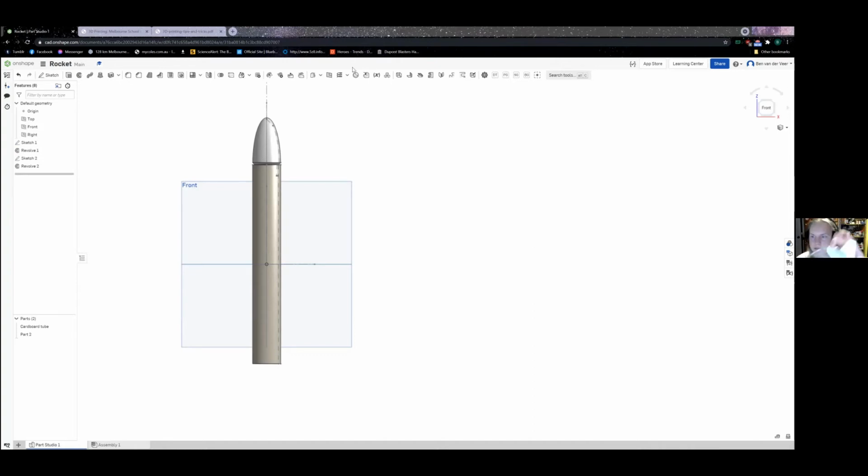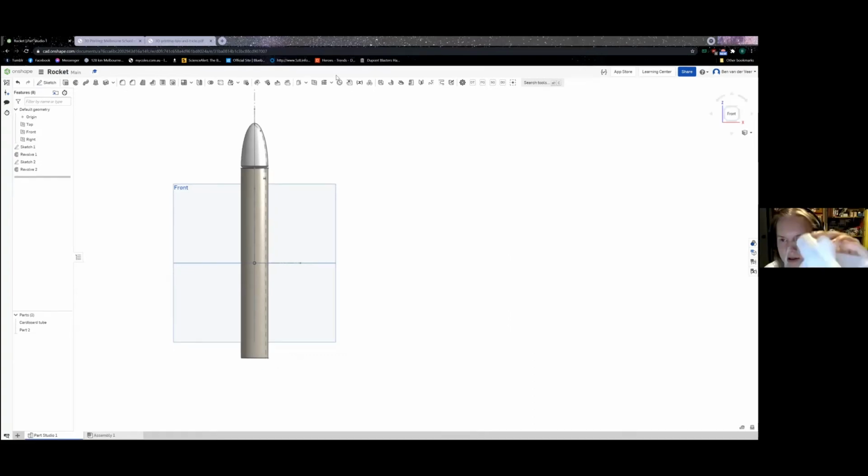But basically the things you need it to do are, of course, have fins so that your rocket is stable. It needs to fit into the cardboard tube nicely. You need a tie down point for your parachute line. You can see here I've just made a hole in the structure that I can tie that off to. It needs to hold the motor.